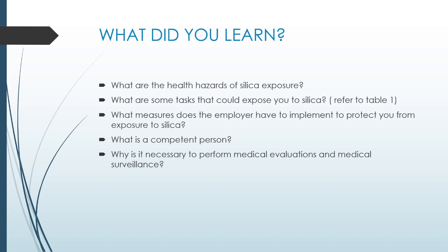And then what measures does the employer have to implement to protect you from exposure to silica? Like we went over, we do the exposure monitoring. We have to have a competent person. We have to have a program. We have to have these training times and things to protect you from the exposure to silica. What is a competent person? Remember, a competent person is someone who has the knowledge and skills necessary to identify a hazard and the authority to do something about it. And then why do we want to perform these medical evaluations? Why the medical surveillance? We want to make sure you're not being exposed. And if there's a potential for overexposure, we want to tell you there's a potential and here's what we're doing about it.